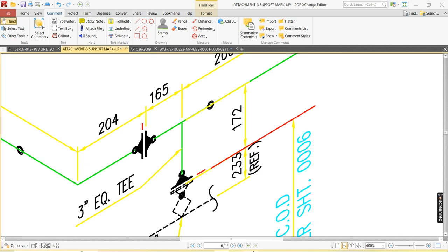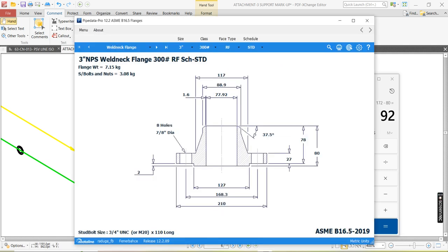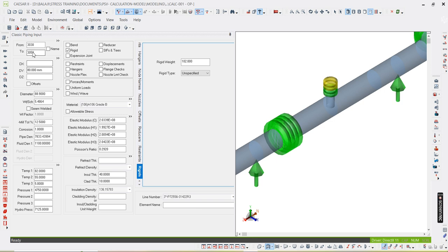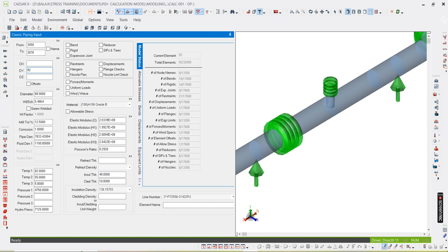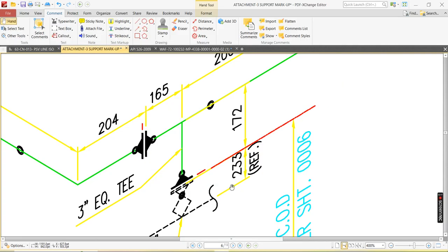as per this isometric, if you go, it should be 172 minus 80. Whether we are checking correctly, the dimension is 80, no? So if you enter 92, I will show you what will happen. 92. So one bend, okay. And here a flange is there. So select a single flange. This side also a flange is there, you see.